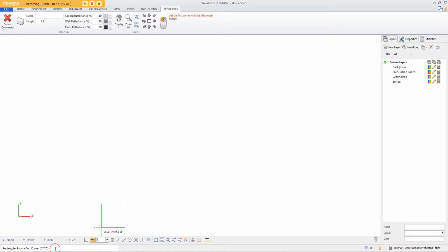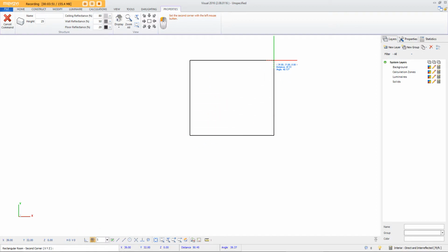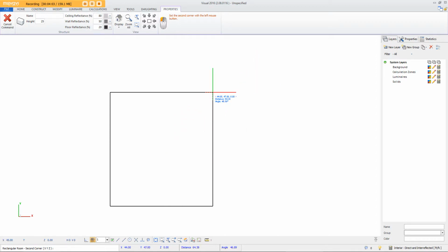So we can start here with the rectangular room. I like to find 0, 0, and that'll bring me to the bottom left corner of my drawing. So 0 space 0, enter, and then I can bring it along. With this being a perfect square and we only need one dimension, we could easily put in the next X column, which would be 240, and the Y, which would be 396, or we can find it.